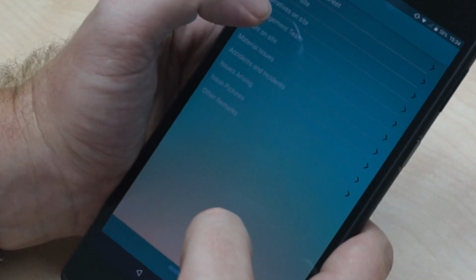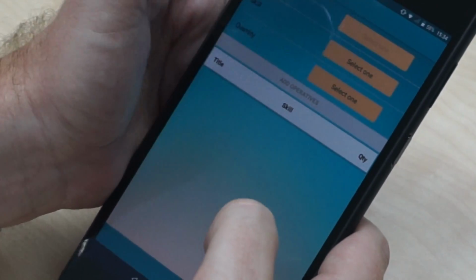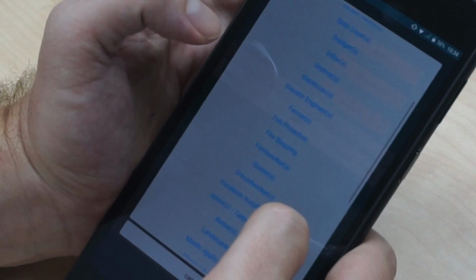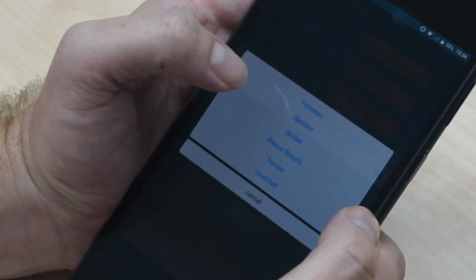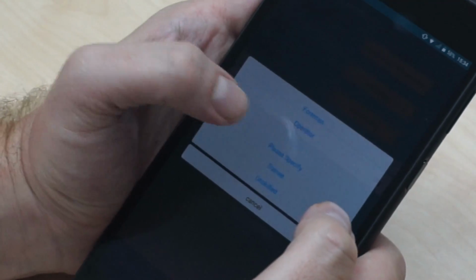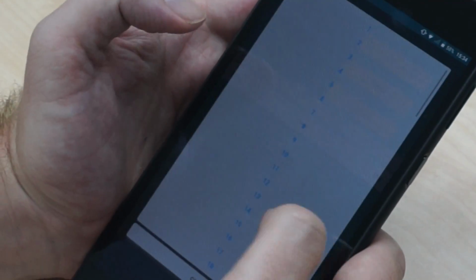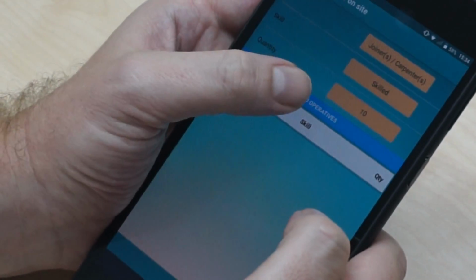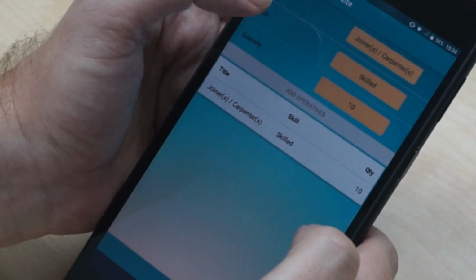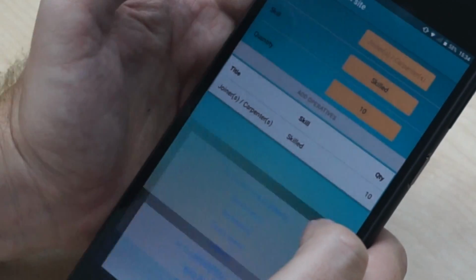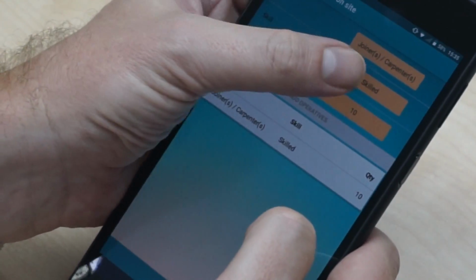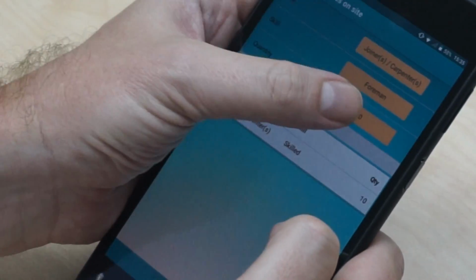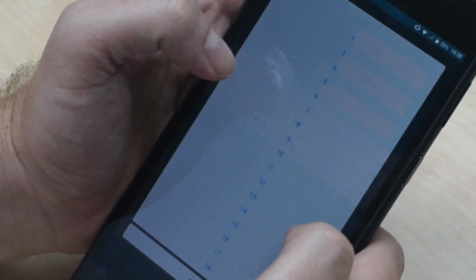We now move on to operatives on site. We select from the title, because we're dealing with a joiner. We hit joiner stroke carpenters. The skill, so there may be skilled, trainee, operators, foreman. Let's say skilled, and we have 10 skilled operatives. We then add operatives. Because we've got 10 operatives, chances are we'll have a foreman. So we click on joiner. Foreman, and we've got 1 foreman for the 10 skilled workers.